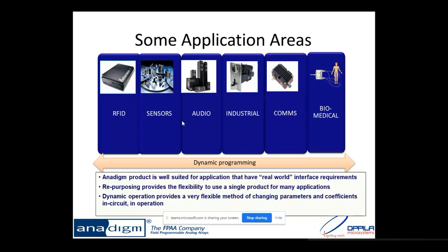One more important thing is that inside the FPAA we can implement different filters. Chebyshev filter, as I already told, Butterworth, almost all different filters can be implemented inside the FPAA. So in audio signal processing, you can use different filtering techniques to eliminate the noise or add the noise. As a demo, you can implement different filters inside the FPAA, feed the audio input to those filters, and try changing those filter parameters. So it can be useful for audio signal processing. Audio signal processing is one of the applications. That's it.